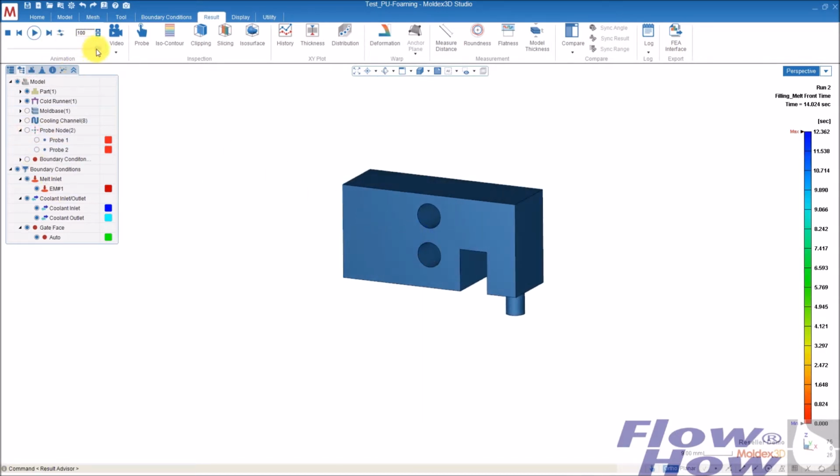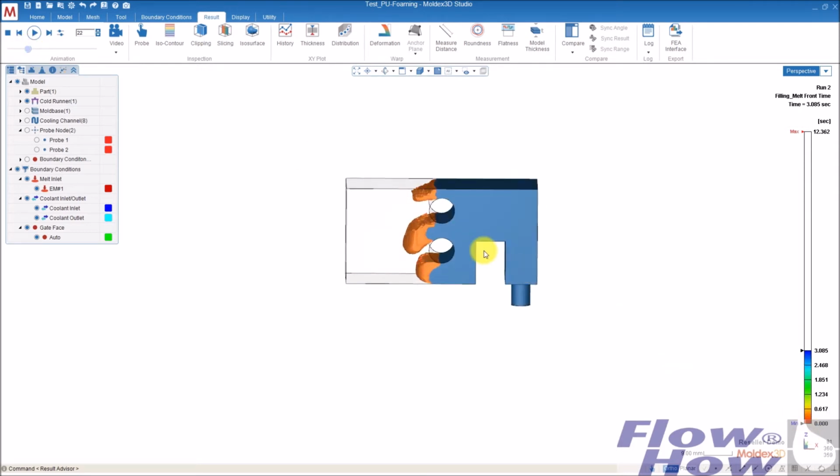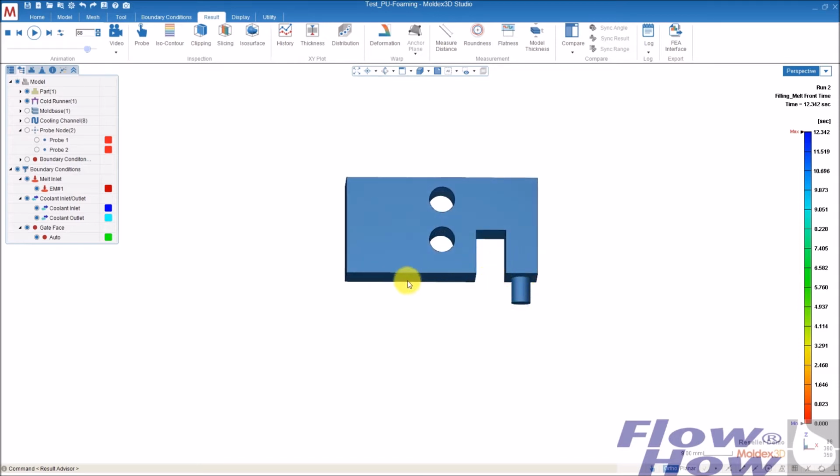So as you can see, the filling is going up here, and then it fills out, and the gravity is set minus, which is dragging the melt downwards, and then you have like a splash of, not water but material going up and surrounding this. So maybe it's not that clever to have a runner like that and place here. Maybe it should be placed out here.